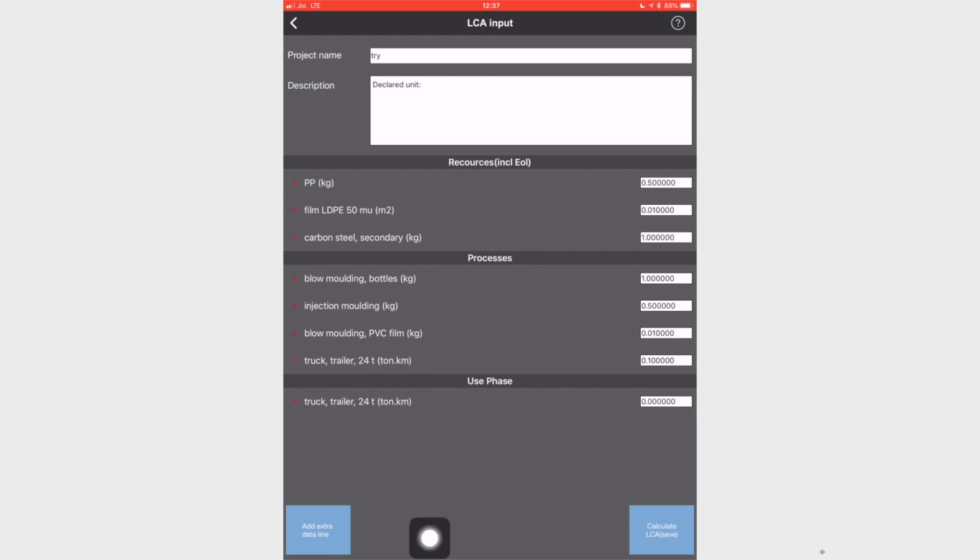What it helps you is, you do not have to create the whole thing from new just because you wanted to check by changing the material. Always remember, when you change the material you also have to change the weight, because if a bottle requires 1 gram of polyethylene terephthalate, it does not mean it requires 1 gram of polyethylene, because the densities of the materials are different.